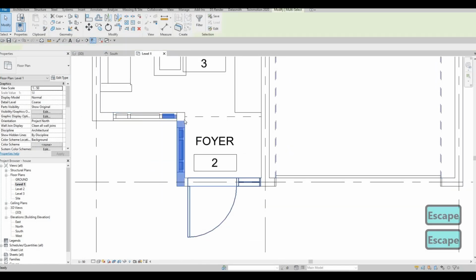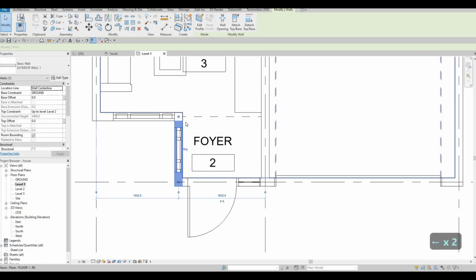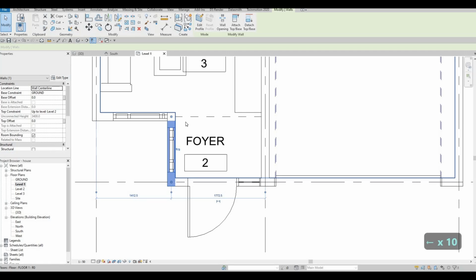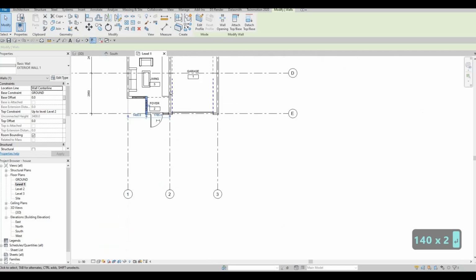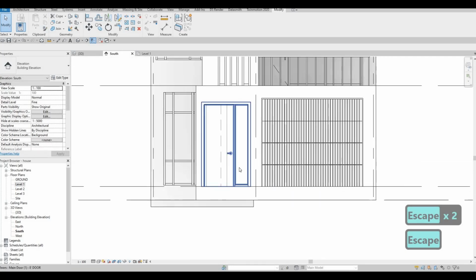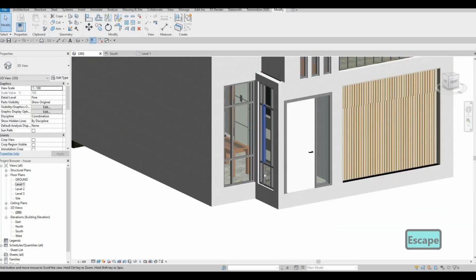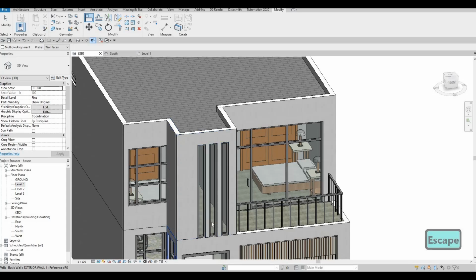What I want to do is move this wall as well so that it's not that cramped on this. So maybe 1400 is enough from this grid line, this is number 1 grid line, and we'll have this part right here. So I'm happy with that. So a bit of a change, and then we just need to align it from the top. There we go.